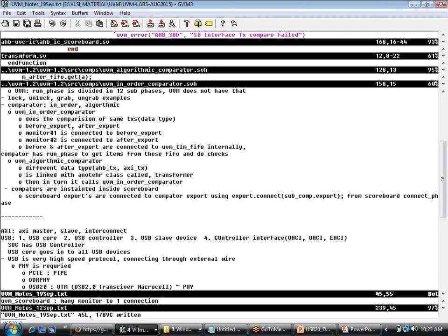So there will be a receiver to collect the data. Then we need to buffer the data. The data comes in a serial fashion. In USB there are 4 wires: V plus, V minus, and D plus, D minus. D plus and D minus carry only a single bit of data, in differential format. That needs to be converted into the parallel format that my laptop requires. My laptop inside doesn't work serially; it transmits data in a parallel fashion, 64-bit or 32-bit. This work is done by the PHY.